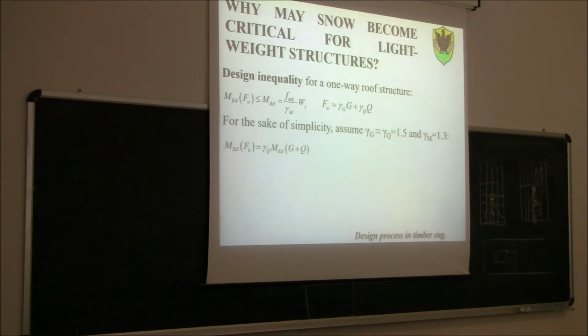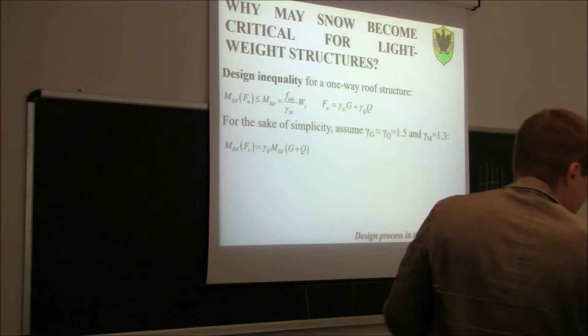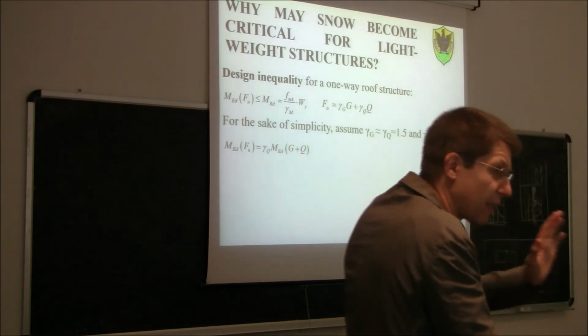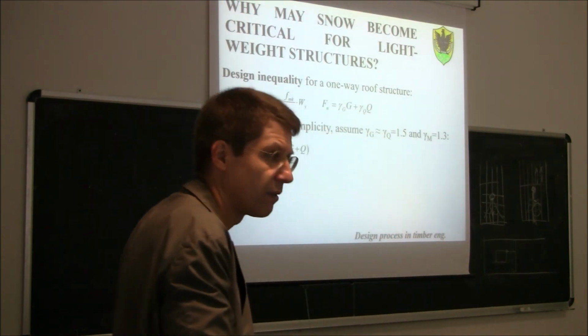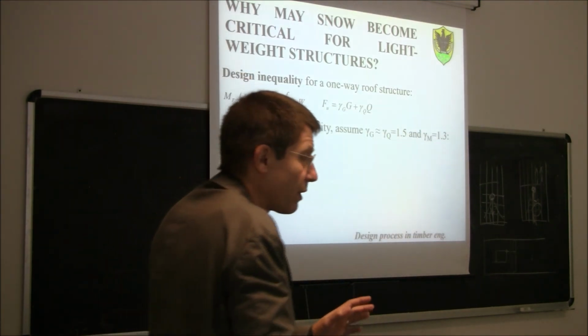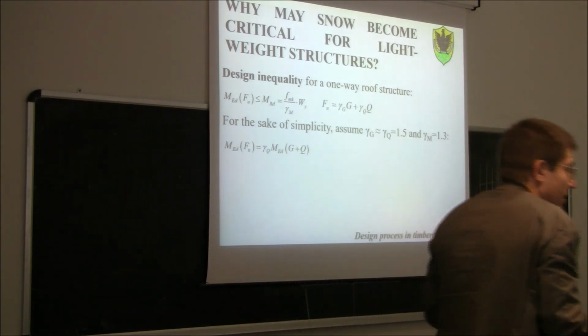We can write that, since in the structural analysis we usually do a linear analysis. If you remember, we use the plastic analysis only for calculating the capacity, if the material is plastic. For timber, we will not even do a plastic analysis here, because we will consider timber as an elastic material.